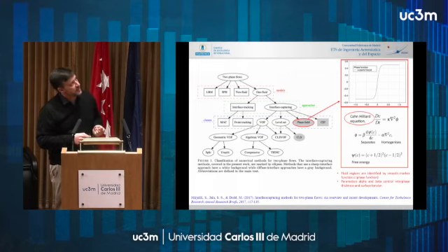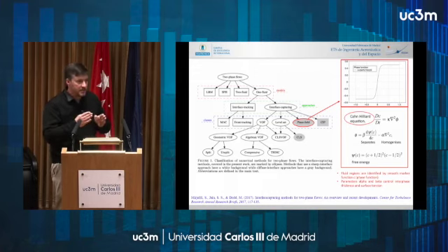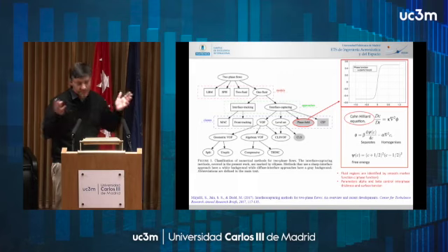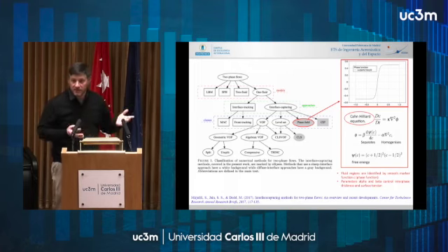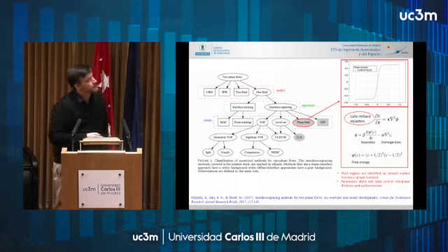And this is very advantageous in terms of higher order methods, because if we have an interface that is very sharp in a higher order setting, you can imagine a Fourier method, you will get Gibbs phenomena. You will get oscillations, you will get instabilities. However, if the interface is smooth, as in this case, then the higher order method is well behaved, you can refine at the interface, everything is nice and smooth.